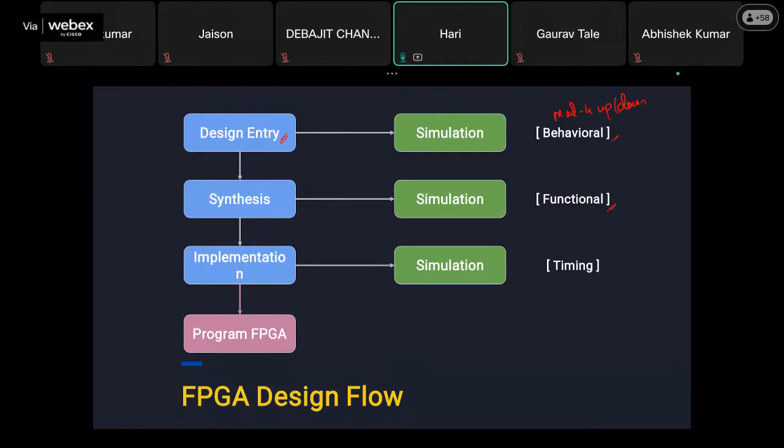Once you write a program, if we are using the Quartus tool, it will synthesize that particular program. Synthesize in the sense that it will convert the algorithm into a hardware block. That hardware block will not contain a redundant amount of code. Assume you are using a lot of unnecessary variables. In hardware, you will not have that much space to accommodate everything. So your tool is smart enough to understand that you are not using those variables, and it will chip them off. Basically, it will not synthesize those blocks and will use whatever is required. I will show this in later slides.